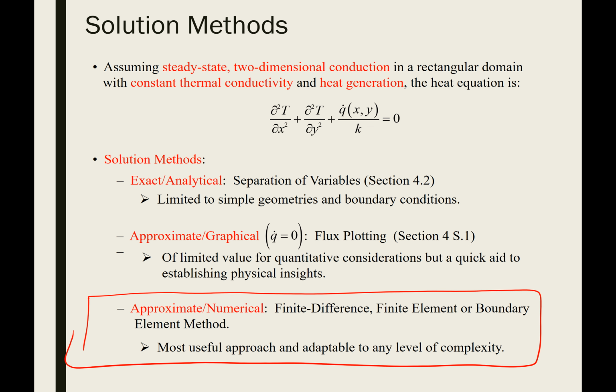Well, if you have a fast enough computer, you can keep those blocks to be of a finite size, but really, really small. Then, solving your system, you can actually use a computer to solve that energy balance for each individual little cube. It's still an approximation, but you can figure out what the temperature of each individual little cube would be, and you can get these really detailed maps of how temperature varies through your solid.